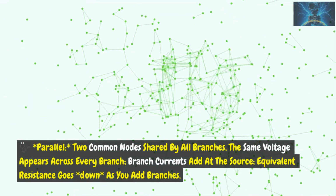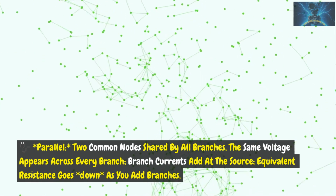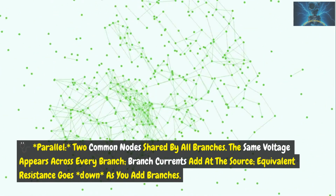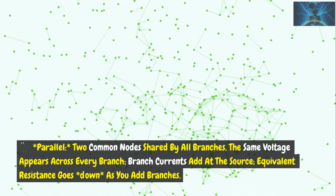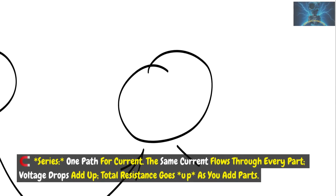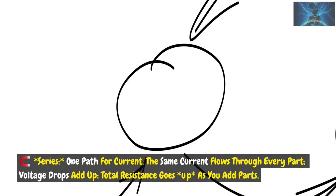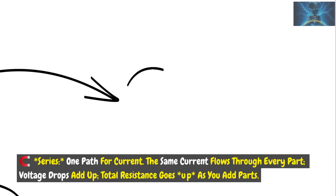Parallel. 2 common nodes shared by all branches. The same voltage appears across every branch. Branch currents add at the source. Equivalent resistance goes down as you add branches. Series. 1 path for current. The same current flows through every part. Voltage drops add up. Total resistance goes up as you add parts.